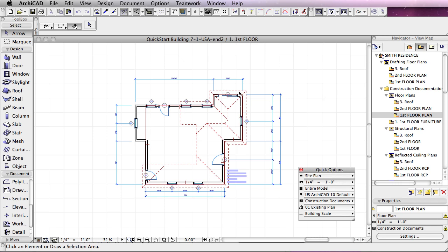Now we're seeing just the walls, the exterior walls and the roofs, and it turns off the interior of the building. Now if you're working with the International Metric version, then you also will have a site option, but you'll need to change the layer combination to show the walls in order to coordinate the survey. I will repeat the exercise I'm about to do, bringing in the survey, with the metric version. So first we'll do the US version and then we'll repeat with the metric.